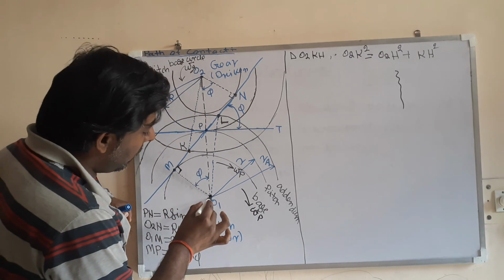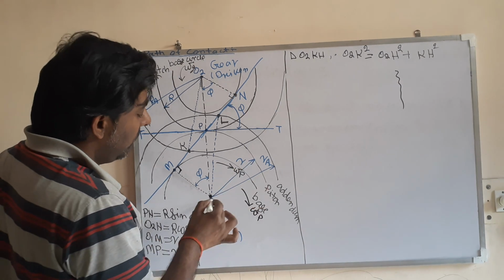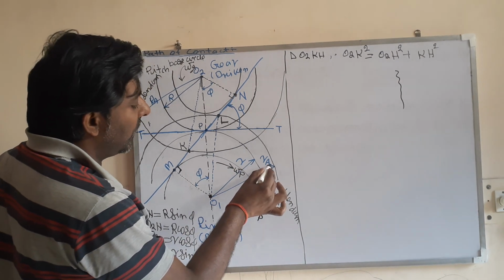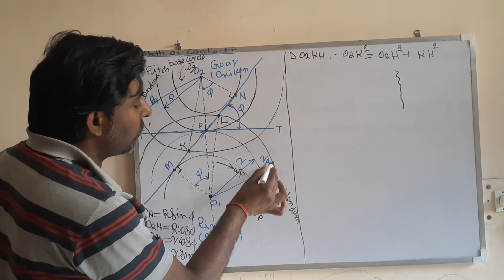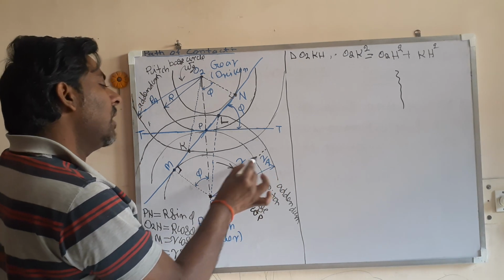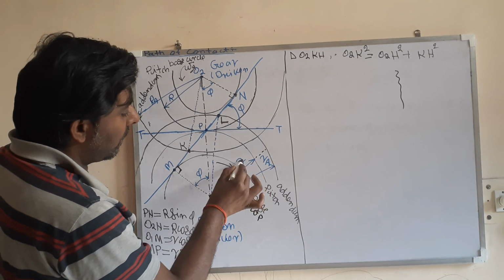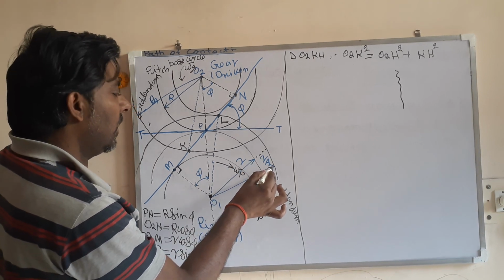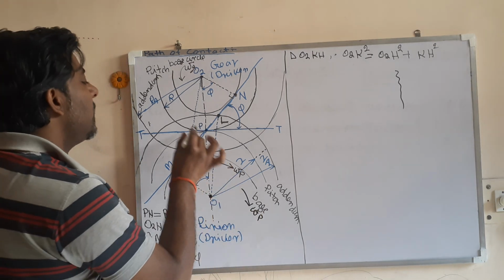Similarly, this is the pitch circle radius of the pinion, and this is the addendum radius of the pinion. To get the addendum radius of the pinion, this will be the addendum height. So when you add the addendum height to this pitch circle radius of the pinion R, you will get the addendum radius for the pinion.